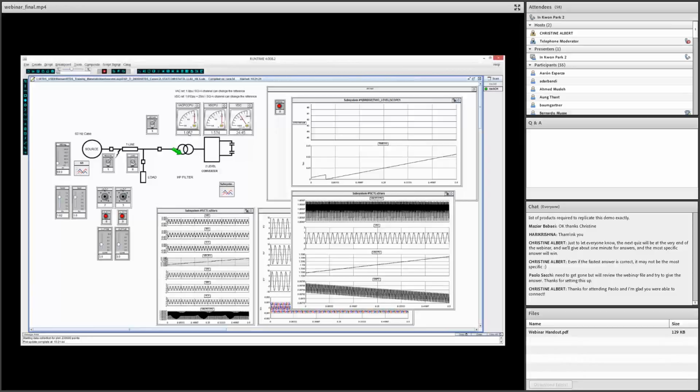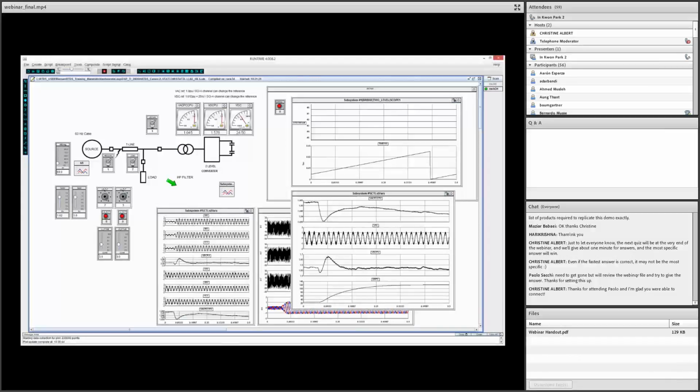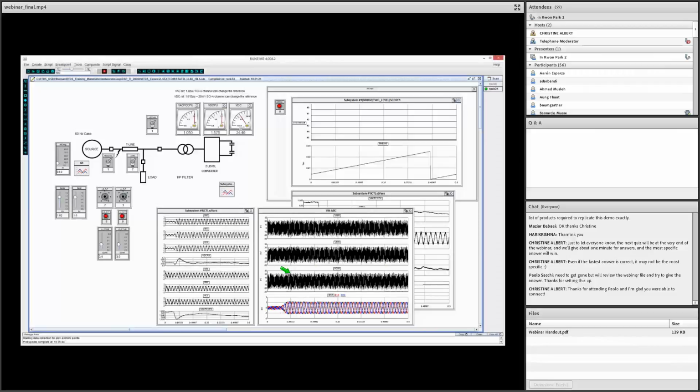And we do the same as before. We just put in the load to see how the entire system reacts. And as you can notice from this Q production curve, the Q production goes from a low value to a high value. Then at the same time, the branch current is increasing because the STATCOM is now producing a higher amount of reactive power.